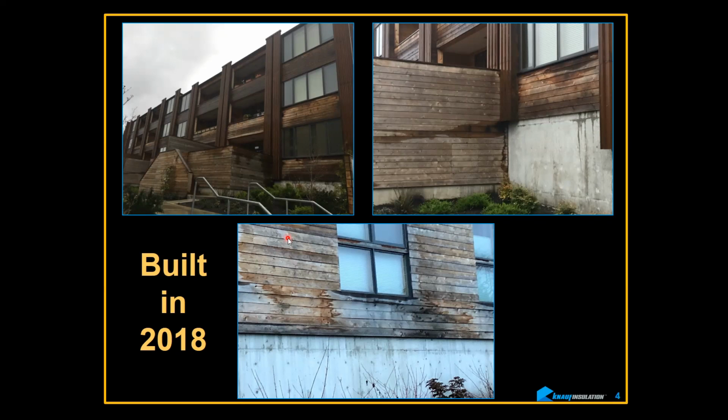And then behind the gap, they have their rain screen. And then behind the rain screen, whatever that space is, they have roll goods, a material product that's supposed to protect against that, but it's not designed to protect against driving rain and high winds. That's one of the reasons I don't like this, because you're deliberately bringing water into where you don't want it, instead of trying to keep it out and dealing with moisture that gets in instead of bulk water. And then the other thing is that these get clogged up with bugs and all kinds of dirt and everything else. So what's the point?